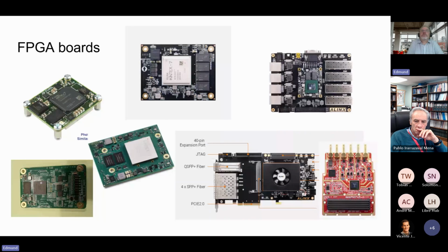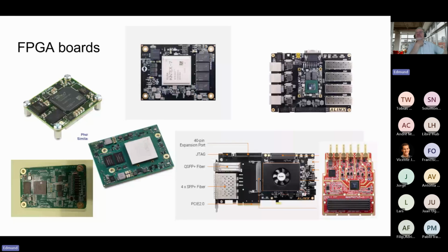And those connectors also have the capability to transfer much higher speed. For example, on the right upper corner, you see a board which comes with 1 gigabit SerDes, and the lower end corner is a Kintex board which even has 10 gigabit interfaces.